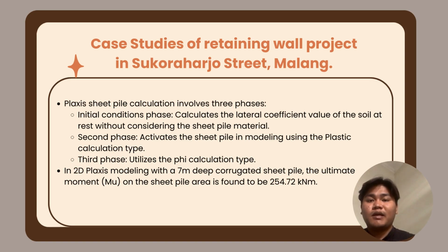And it starts with calculating the lateral coefficient value of the soil at rest without considering the sheet pile material. Next, activate the sheet pile in modeling using the plastic calculation type. And the last one is to utilize the phi calculation type.